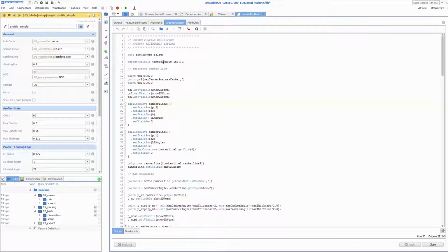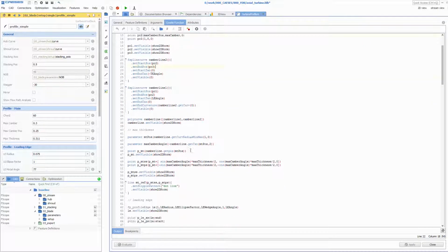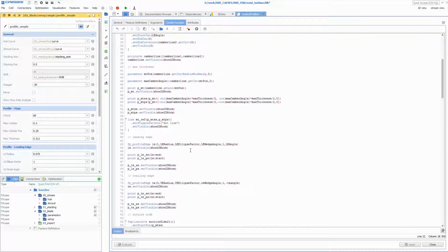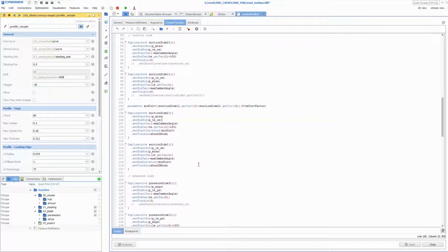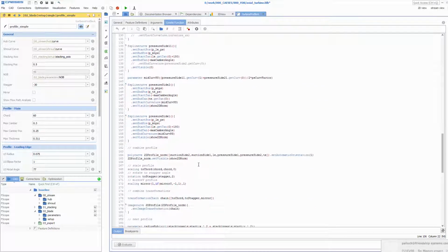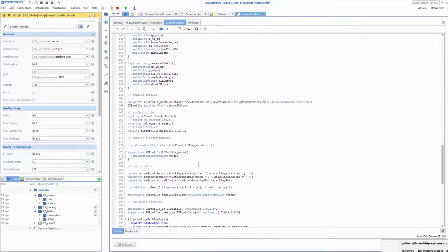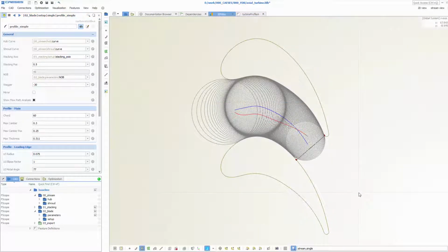In the next step, you simply use this parameter input and define how the profile is set up with it. For this task, there are plenty of flexible curve types in CAESES. In addition, you can define helper functions, mathematical expressions, control statements such as loops and if-else branches, import sectional point data, and so on. The flow path can also be analyzed and visualized by using the inscribed circles routine.